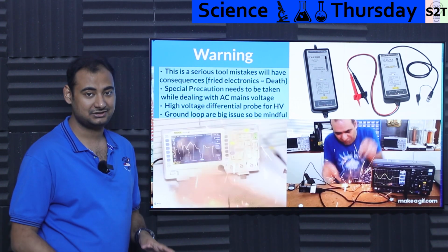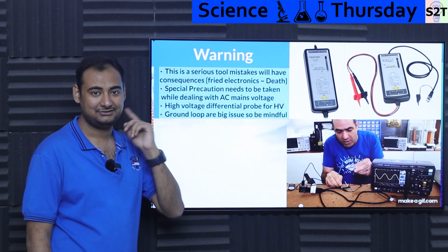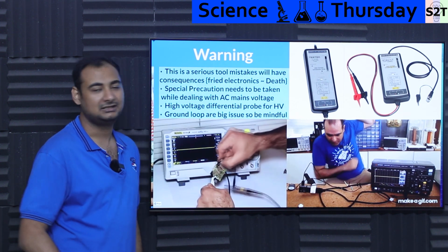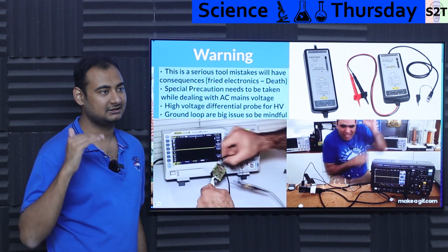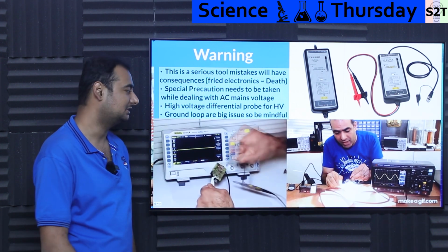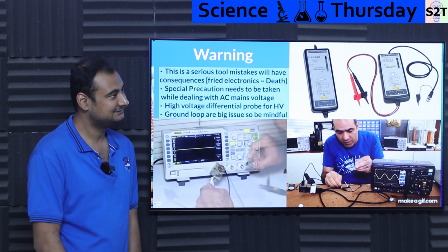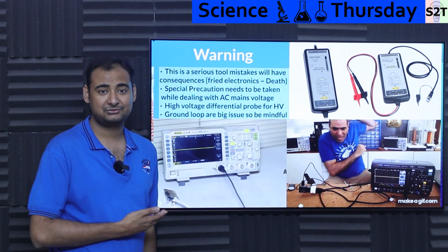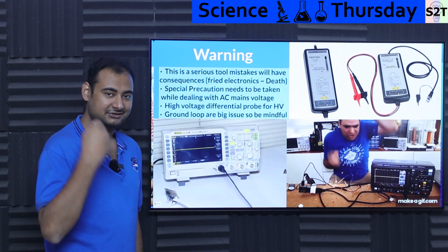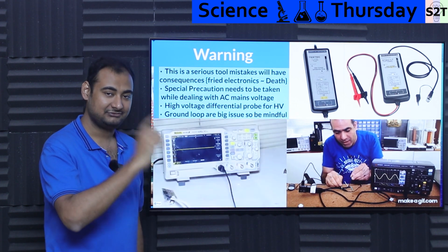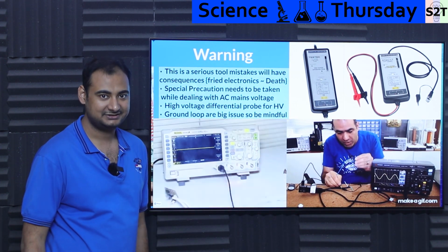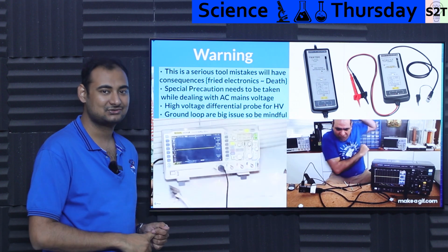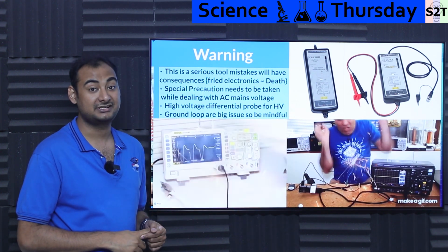So it's very brutal issue because ground loops are a big issue. We do not think about it, ground loops, unless you are an audio engineer. Audio engineers, they talk and breathe ground loops, but for normal people, you and me, we do not talk about it. And it's a very big issue. If I'm working with Arduino and Arduino is connected with USB, with my computer, the computer has grounded it, meaning there is actual ground. So if my oscilloscope is also grounded, now I have risk.